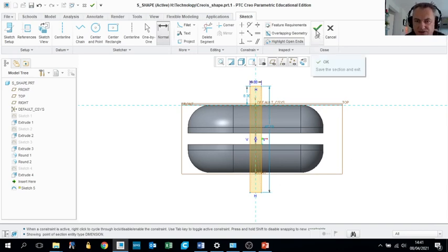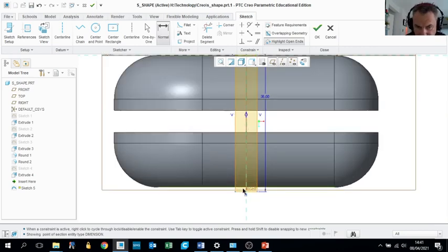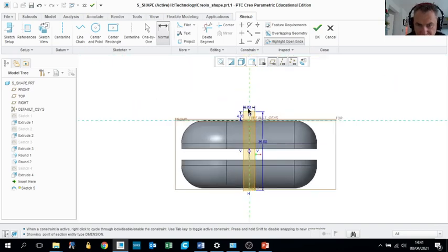Then I'm going to, doesn't need to be that wide. We know that it was 30 millimeters front to back. So if I say 35, I know that it will clear it. Okay, so I had to reduce that number to make that sketch come across and clear the model. Okay, so it's cleared it, it's out here, and it's out here.